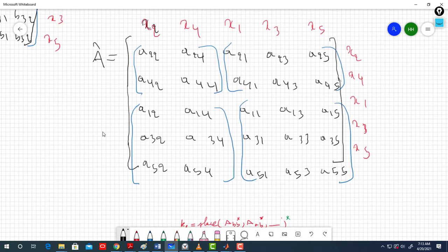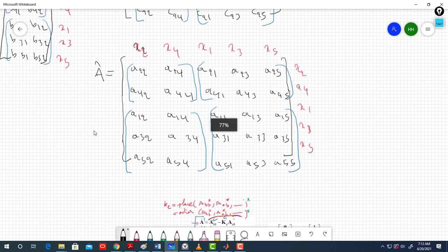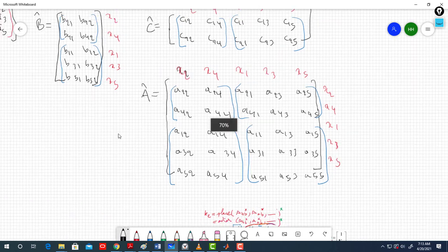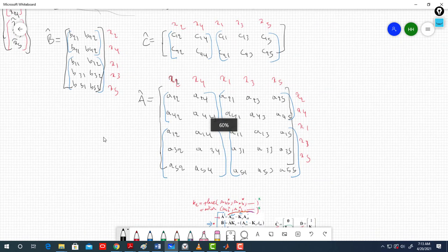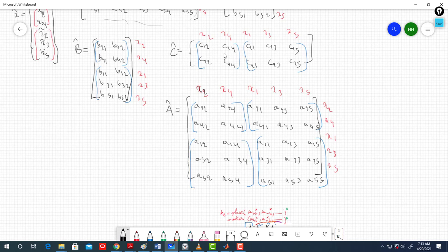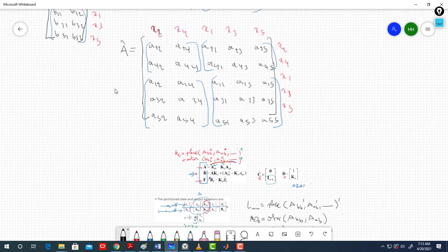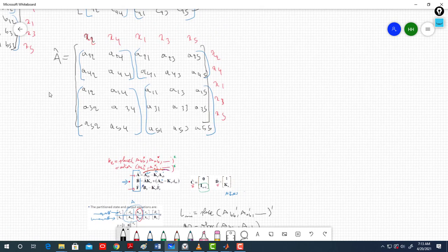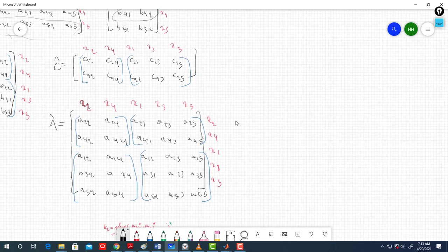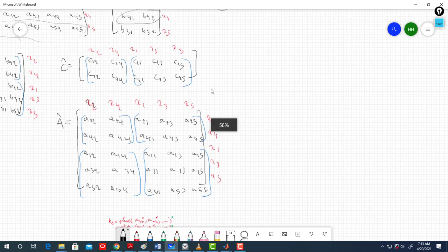Alright, so let's go based on it. Before I go into MATLAB, in MATLAB we will build the matrices first, because it's the first step. Once we build the matrices, we compute the minimum order observer gain, so we can know our minimum order observer. Just before going there, I want to show you iteratively how I can find A hat in MATLAB.